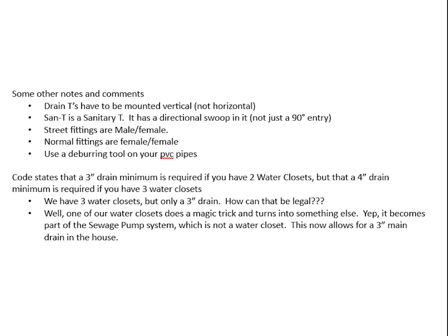Some other notes and comments. Drain tees have to be mounted vertically, not horizontally. Sanitary tee is a sanitary tee. It has a directional swoop in it, not just a 90-degree entry. Street fittings are male and female. Normal fittings are female-female. Use a deburring tool on all your PVC pipes.